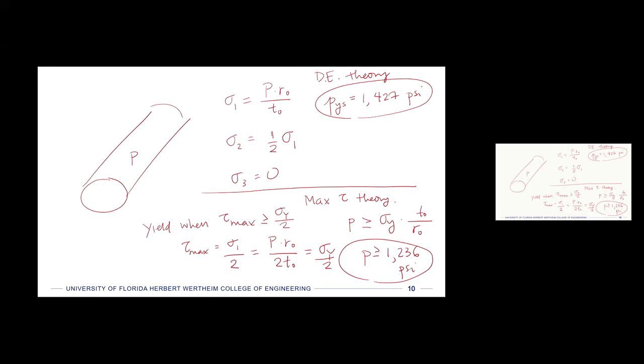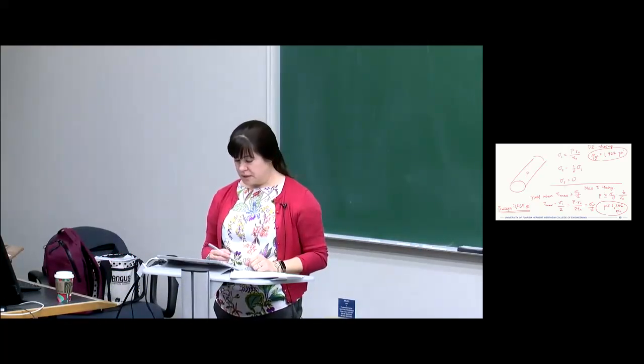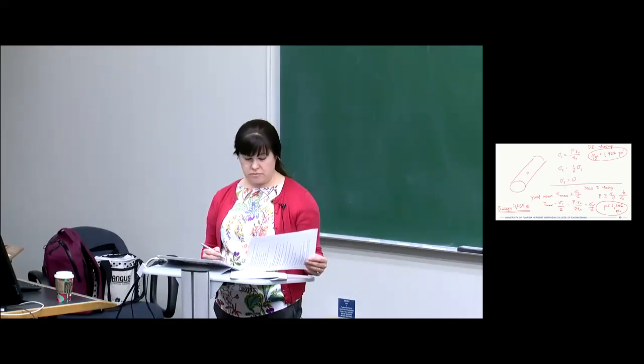If we go and think back on how we calculated the pressure that you would have to keep pumping it up to get the plastic collapse, that was 1,455 psi. And that actually does not change, because for that we only used the plastic strains, and sort of how it gets the K and the N to calculate that. And so I don't believe that that would change.